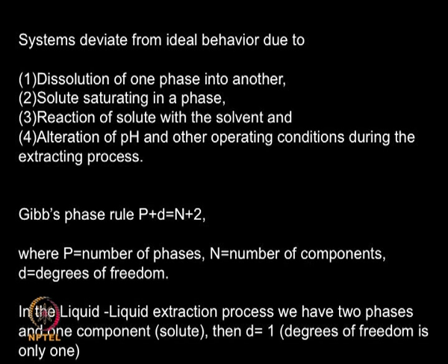Alteration of pH and other operating conditions during the extraction process: of course the pH is going to change, sometimes temperature may change, because you may take a cold solvent and use it to extract a solute from a hot fermentation broth. So these operating conditions also will affect my extraction process, so you will not have this type of thermodynamic equilibrium taking place. So you need to consider that in reality there is a non-ideality, and the streams leaving the extractor are not in equilibrium.